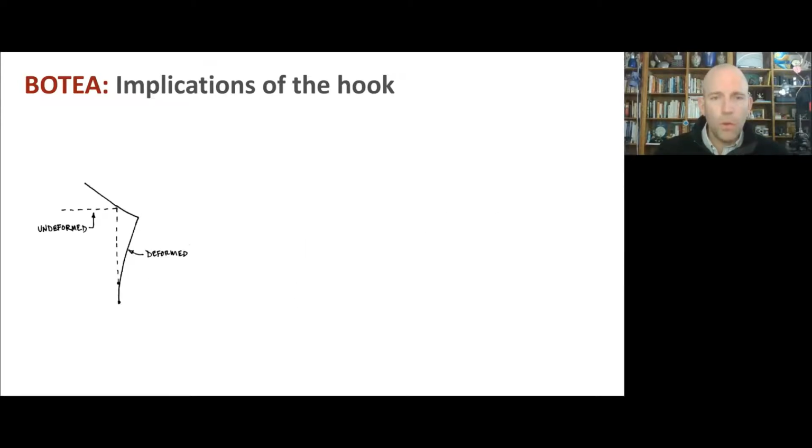So what will that mean about how the table and our part interact? Well, we're assuming a normal force at that contact between our hook component and the table. But if that hook component is right on the corner of the table and we do have a normal force, then that force will have both a vertical component and a horizontal component, right?